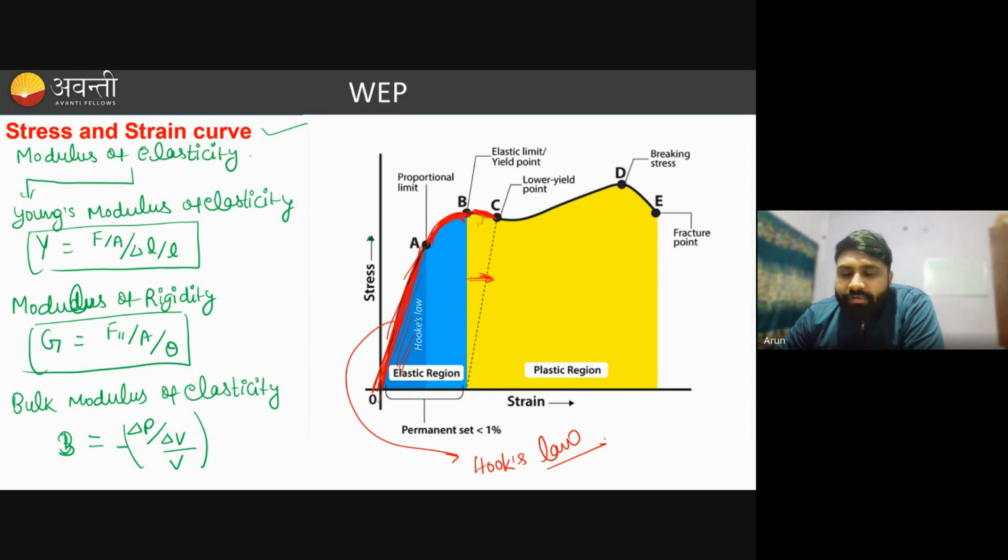And it is because at this point of time, the molecules have separated so far that instead of applying a very large amount of stress, they will show you a kind of elongation behavior with a very small value of stress applied, because at that time the molecular forces are very weak in that molecule. Got it?